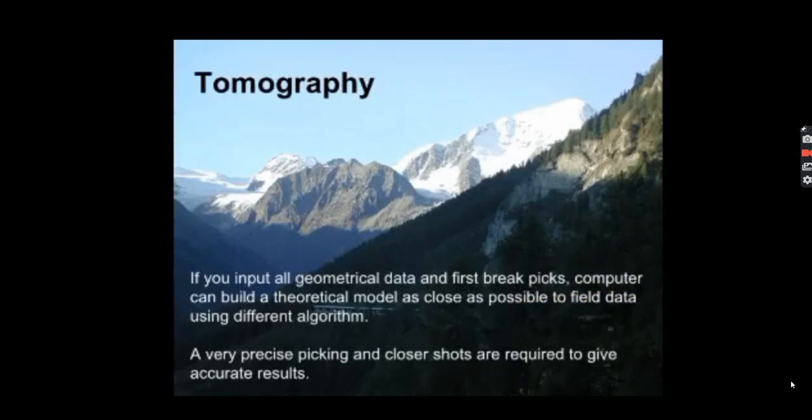Now let's proceed to tomography. If you input all geological data and first break picks, the computer can build a theoretical model as close as possible to field data using different algorithms. Very precise picking and closer shots are required to give accurate results.